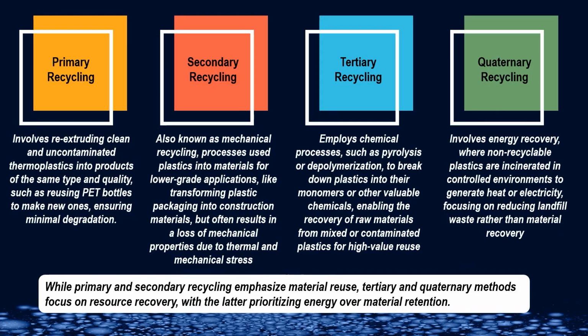So if I do some sort of reinforcement along with the mechanical way to improve some of the properties, then give it some thermal cycle, this adds to the second category, which is called secondary recycling. Sometimes even by reinforcement and heating and melting, I am not able to get the required property. Then I use some chemical way of recycling.